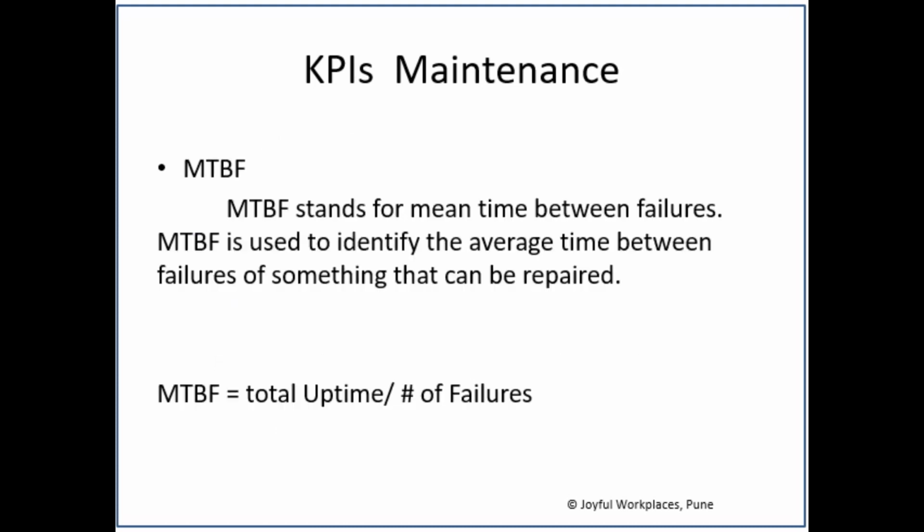Let's understand another KPI of the maintenance, that is MTBF, which stands for mean time between failures. So MTBF is used to identify the average time lapse between the failures that need to be repaired. So what is the MTBF in terms of formula? It's total uptime divided by number of failures.